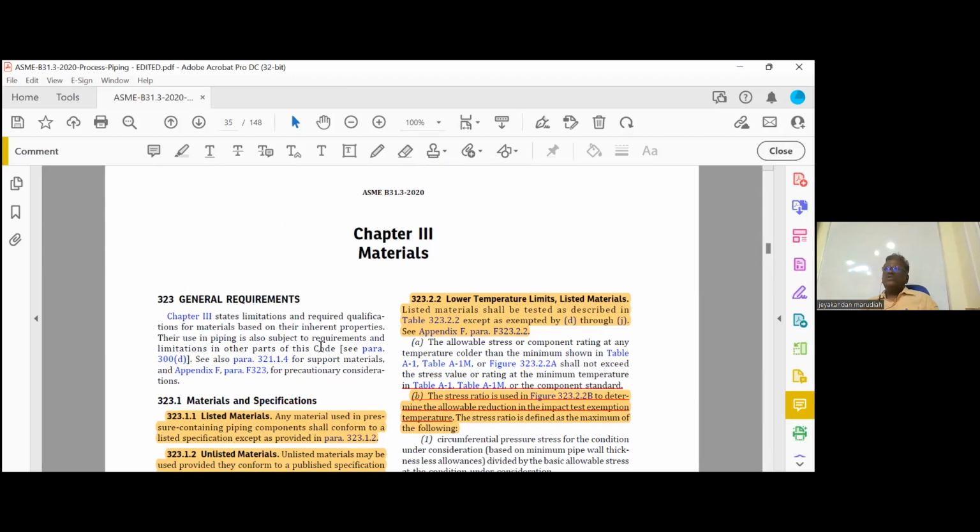Third one is unknown material. Suppose you have a pipe without any details, you should not use it for the pressure class. A pipe without any identification should not be used. Fourth one is called reclaimed material. Reclaimed means you are purchasing an already used pipe. It is allowed by the code, provided it is properly identified and completely clean.